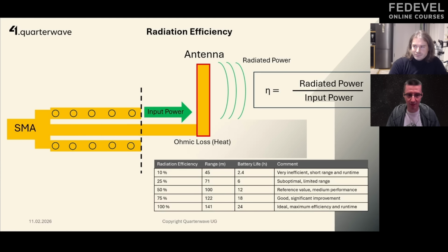So it has to be tuned exactly for the environment, as you said. Exactly. So first, of course, you make your prototype, but the important part is the real-life test. You need to integrate the antenna and measure it in the integration space, and in the end also in the environment where your product is used. So this is very important.